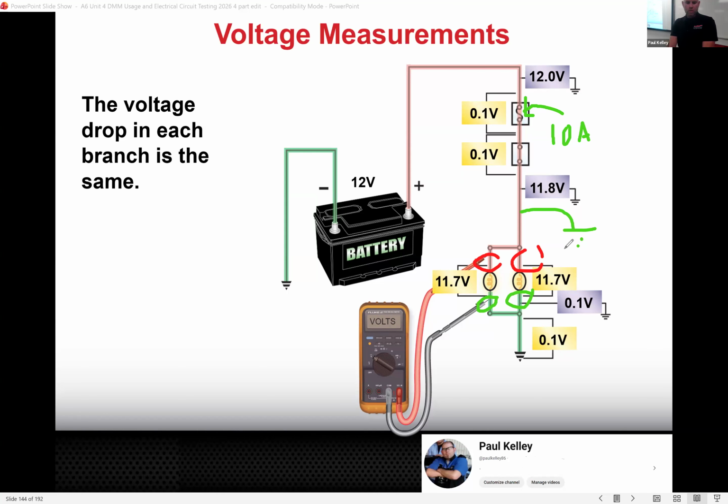What I'd probably truly do is like I showed you at the very end of the last one, how we would diagnose a short to ground. It was a little tough to take in all that. I'd put a bulb across the fuse, and if the bulb lights, that means it's getting 12 volts here, and that means it's getting ground here. And I would just disconnect various points until the bulb went out, at which point I know I took the ground away. I'd just be like, oh, your short to ground is between here and here. I need to inspect further, and I find that Sparky's radio shop sent a screw through the harness and it's grounded or something. So I don't even really do a whole calculation.